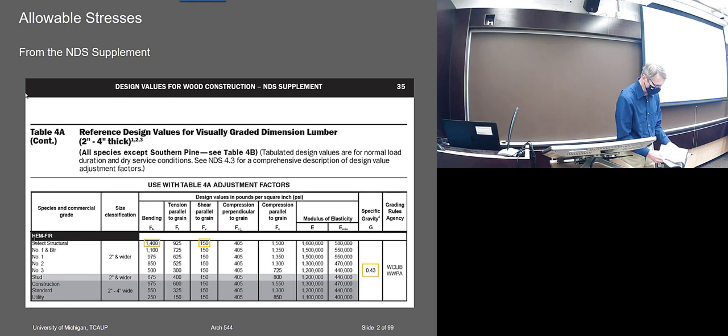And in the front of all those tables, they've got pages that give all the dimensions and the sizes. Also on this, it'll give the weights for a series of densities: 25, 30, 35, 40, 45, 50. So if you pick one of those densities, you don't even have to calculate the weight. It'll give it to you. And right in front of each table, there are a series of adjustment factors that pertain specifically to the tables.